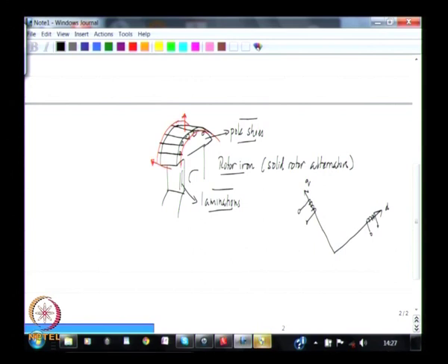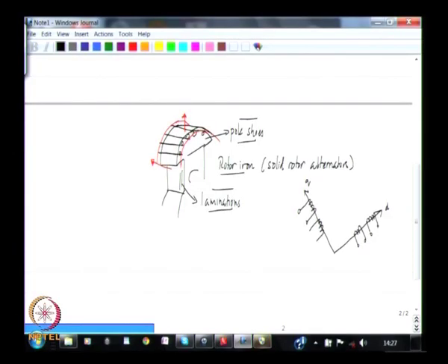In addition, however, if there is going to be substantial induced EMF in the rotor itself, maybe one may go in for additional coils that are represented on the d and q axis, of course being solid rotor and therefore flow of current can be there even on the damper bars, they are shorted, and therefore these coils are invariably represented as shorted ones.